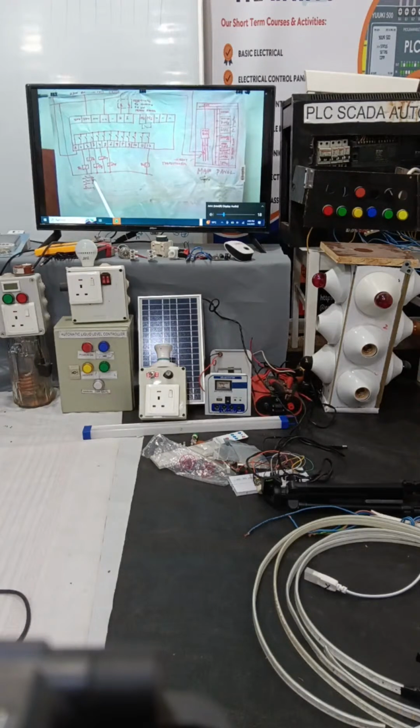In some cases, if the contactor size is small, it directly feeds the contactors. If the contactors are big, or there are more contacts, like in our case where we have 3 contactors in parallel, the load comes to this point. In that case, this contact will burn, and since it is inside the contact, we can repair it. To avoid this, we are using one small relay. It will have only small auxiliary contacts.